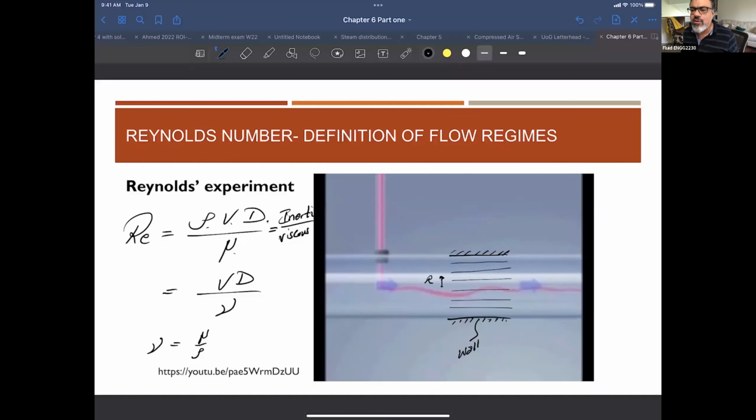So that's why in laminar flow the viscous forces are more dominant than the inertial forces, and that's why you will see the fluid characteristic is defined in this way. And that's why we don't have to run different velocity, different viscosity, different diameter and so on, but now we have what we call a non-dimensional number. Every time we calculate the combination of these parameters, we end up with something that is equivalent for all these cases. For all these experiments, it looks the same just before the Reynolds number becomes about 2000.